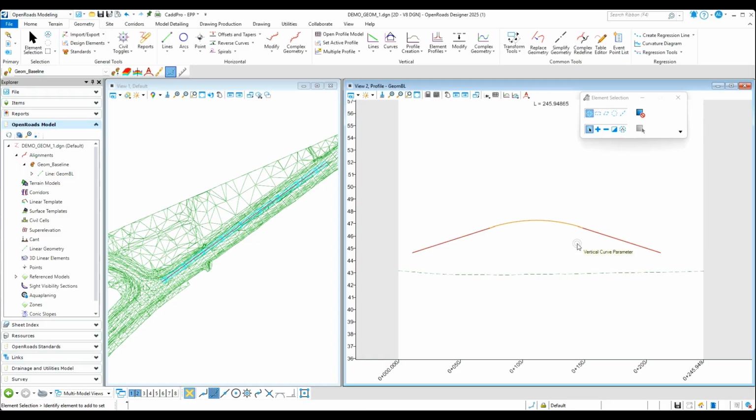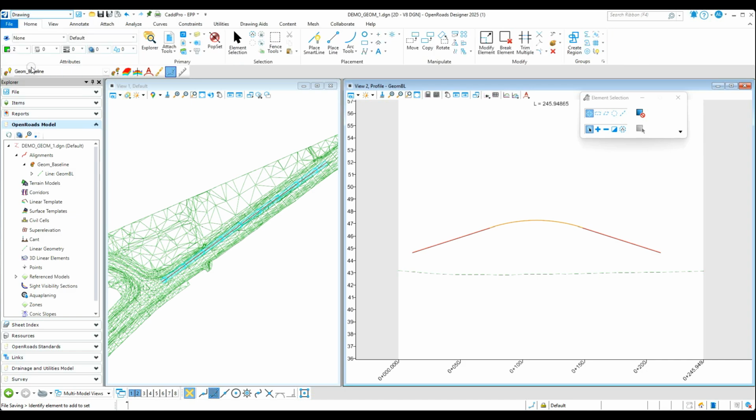All right, tip number 4, inserting a vertex graphically. So we'll go back to our drawing workflow, go to insert vertex, click on that tangent we're after. So I'll insert a vertex there, another one there. We can also delete a vertex using the delete vertex command. So, all right, we've done that.